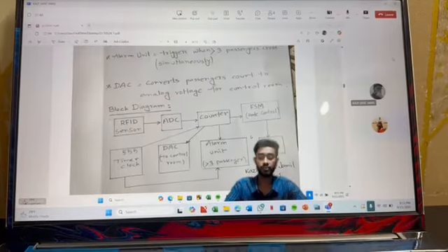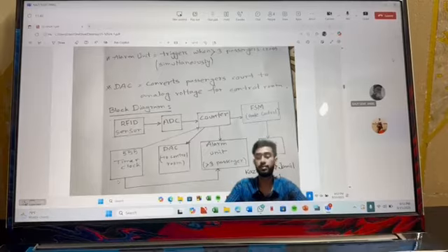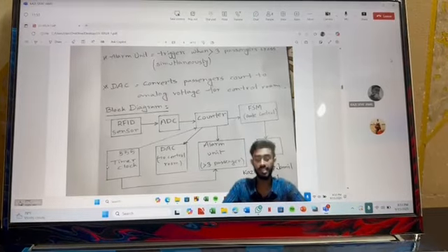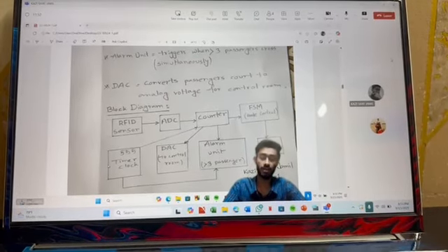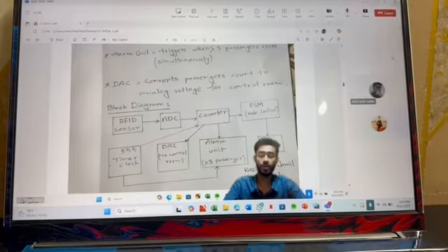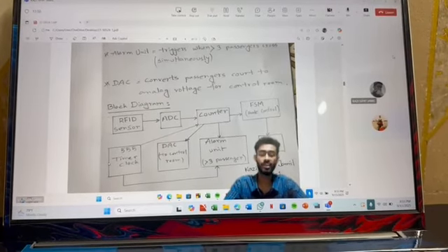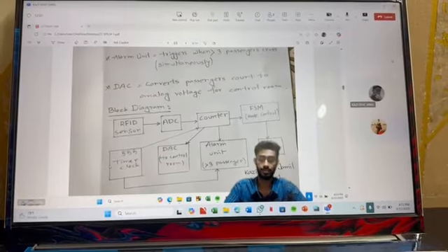After that we use a 555 timer, which provides a steady clock signal. This makes sure our counter and alarm unit work at the correct speed. If something goes wrong, the alarm will trigger a buzzer.